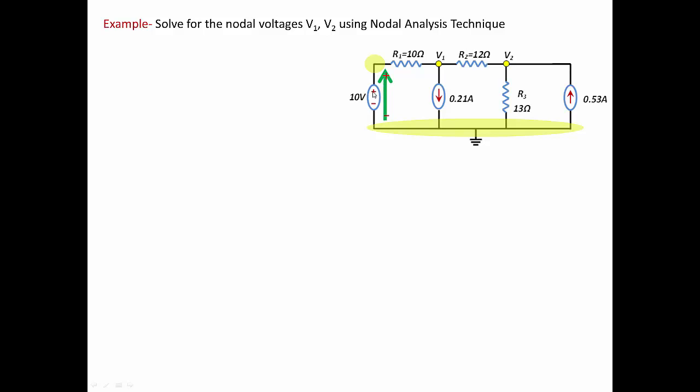If we reverse the polarities, if we make this voltage source have the plus polarity at the bottom, then the voltage at this node is going to be negative 10 volts, because the voltage from this node to ground is then minus the voltage from the plus to the minus. In any case, we have consistent polarities here, so the plus polarity on the top is the same as the plus polarity on the top of the voltage source. Then the nodal voltage is going to be 10 volts.